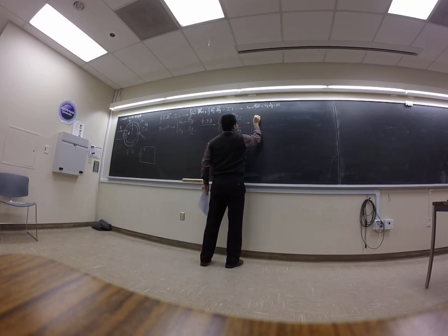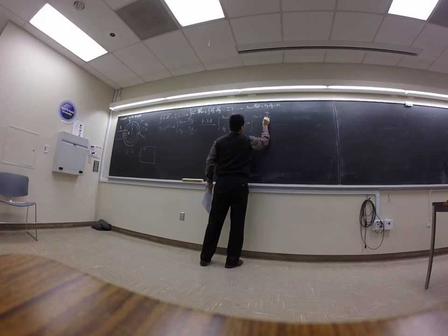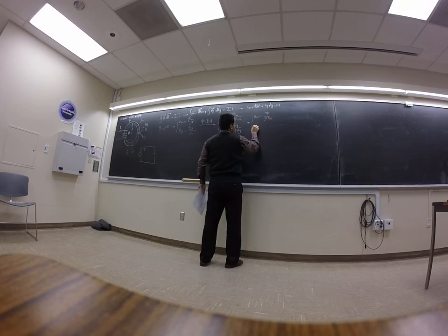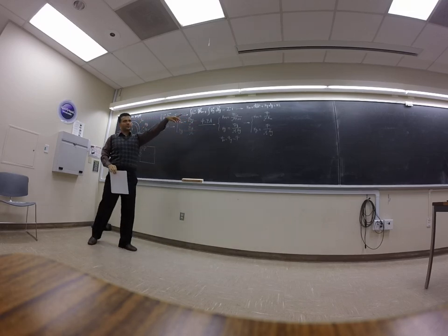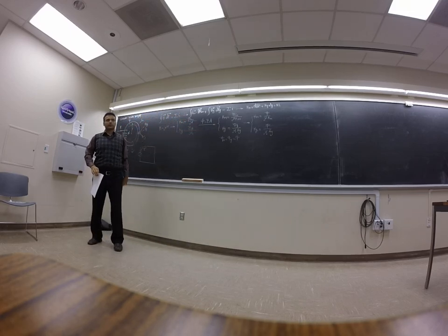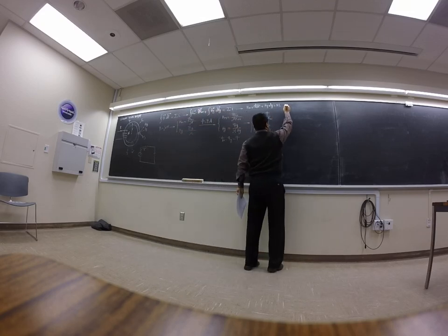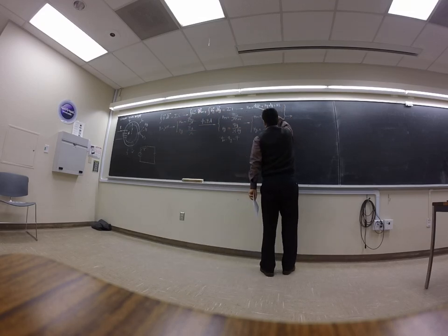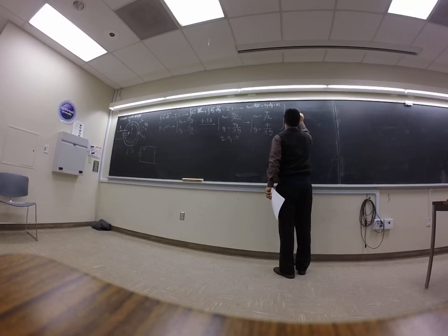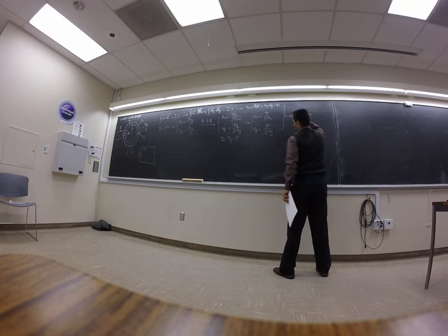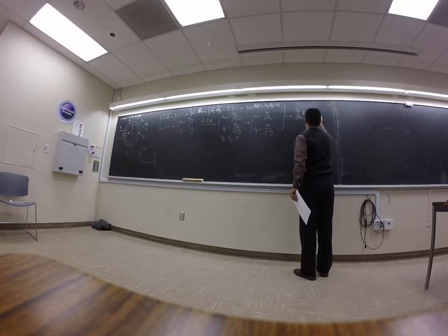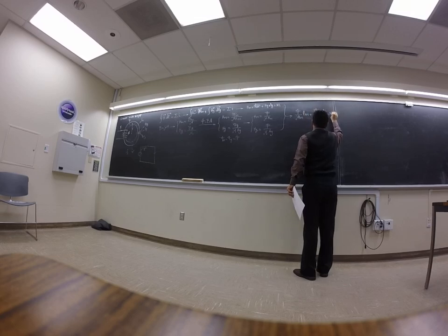So Hm is going to be phi over mu Am, and Hg is going to be phi over mu 0 Ag. Now let's replace this one in the above equation over there. We'll go all this through. So Hm is going to be phi over mu Am times Lm plus Hg is going to be phi over mu 0 Ag times Lg equal to Ni.